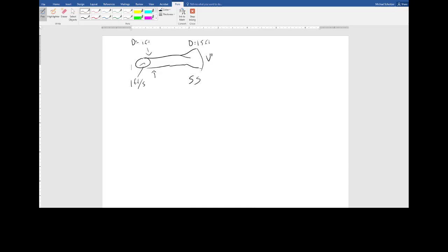What response best describes the exit velocity in the 18 inch diameter pipe? So now this is a conservation of mass problem. So dm by dt is equal to the sum of m dot in minus the sum of m dot out. But we know that it's at steady state with one inlet and one outlet. So m dot in is equal to m dot out. There's really only 3 ways that we know how to find mass flow rates. Area times velocity over specific volume.